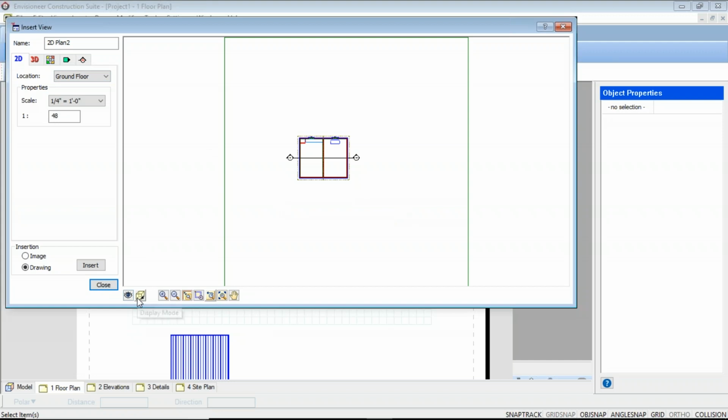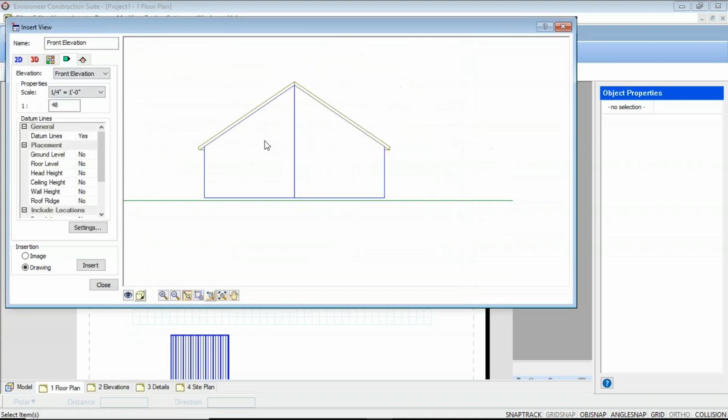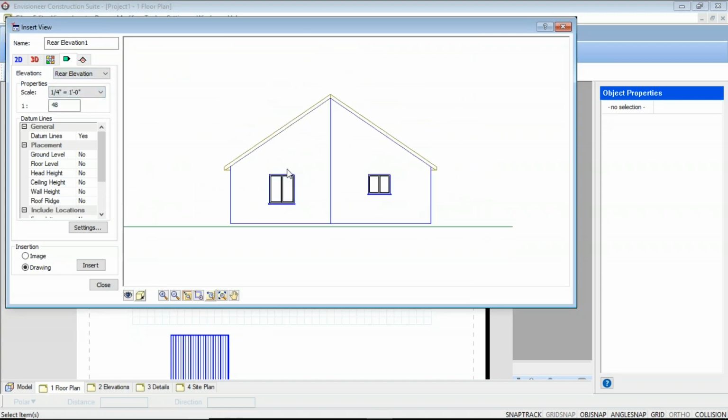framing for this particular model, I would go in and say under View Filter, cancel Elevation View, and then let's actually look at the rear elevation, and then we can go in. Actually, you know what? If you do it this way, it's going to show you the framing behind that as well. So you're always going to see the framing of the wall behind.